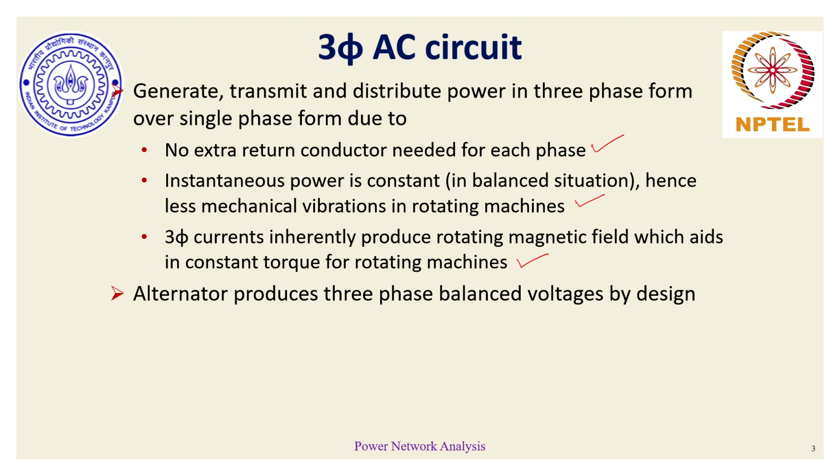So, with these three-phase AC currents, the way the alternators are designed, they inherently produce this rotating magnetic field which aids in operation of rotating machines. And thanks to our design of synchronous generators, it inherently happens. Nothing exclusive needs to be done from the perspective of creating these rotating magnetic fields.